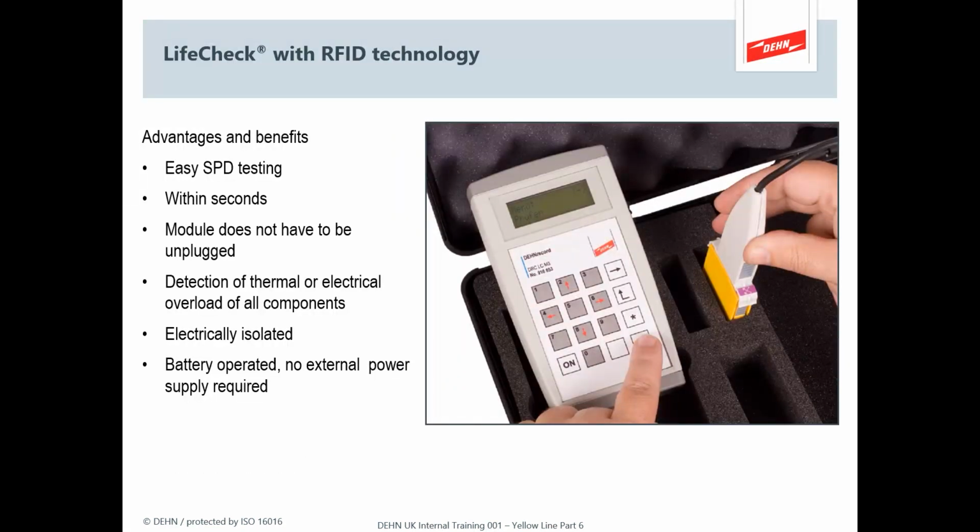I can even unplug it. This could be very handy if I'm in an intrinsically safe or an ATEX environment, where I obviously can't take the tester into that sort of environment, so I can remove the actual SPD plugs, then apply the tester, and then I can go back into that environment without introducing any threat from the tester itself, because it's not ATEX approved.